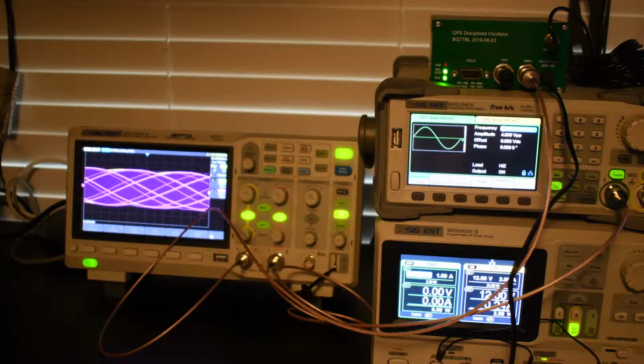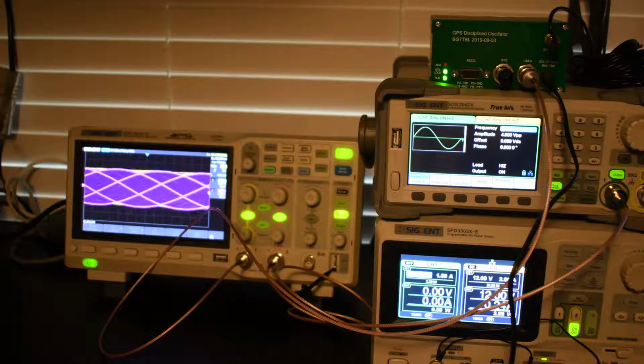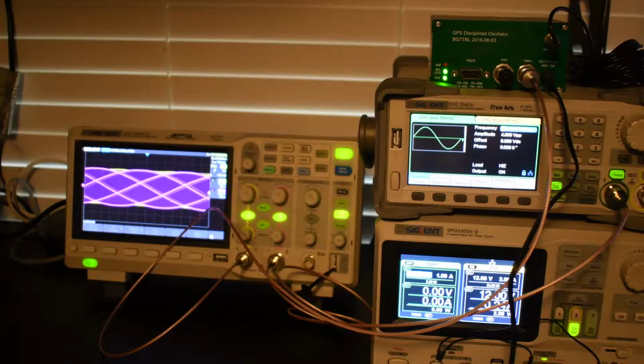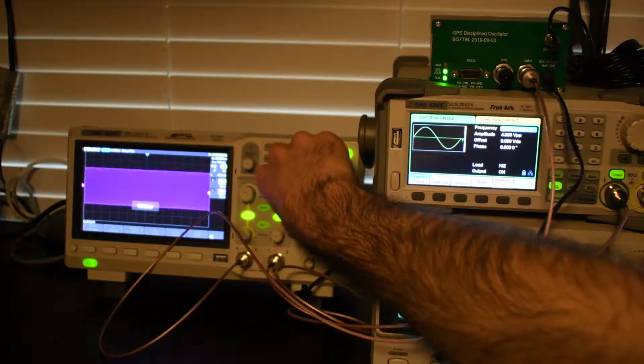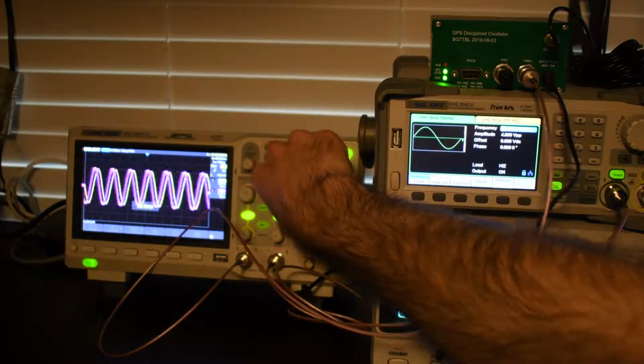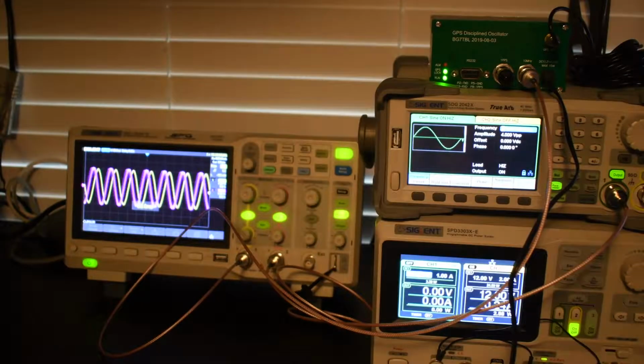But if you do that, it turns out that for this oscilloscope and 10 megahertz sine waves, the best you can do using that method is to distinguish in increments of about 35 or 40 hertz, which isn't good enough because, as you can see when we zoom in close, the difference is probably less than 5 hertz between the two. So we're going to have to come up with some other way to do it, and I'll explain in a minute how we do that.